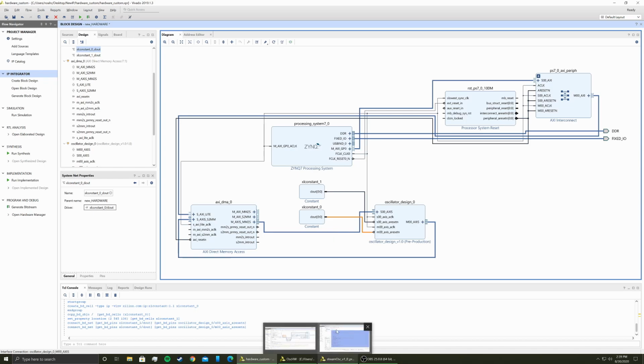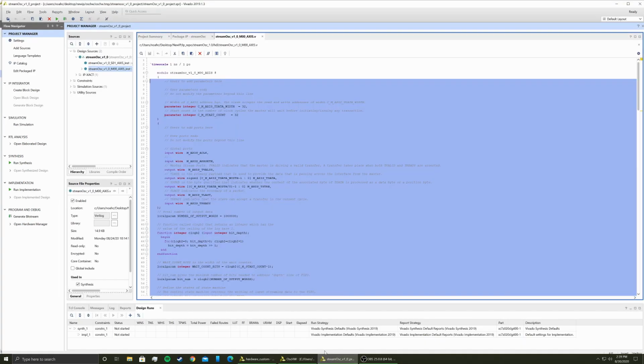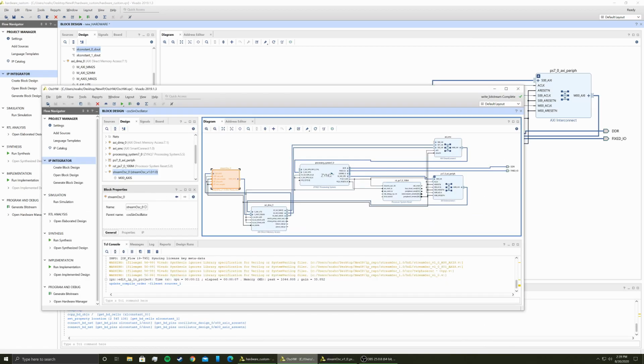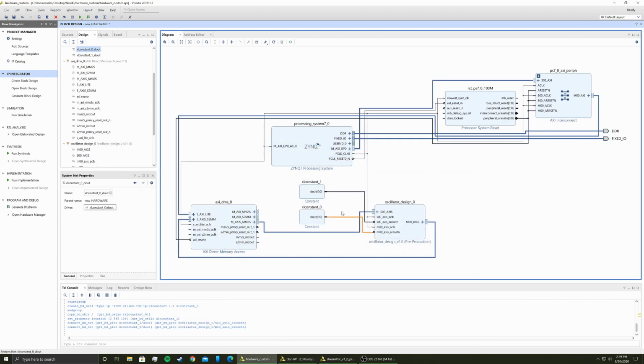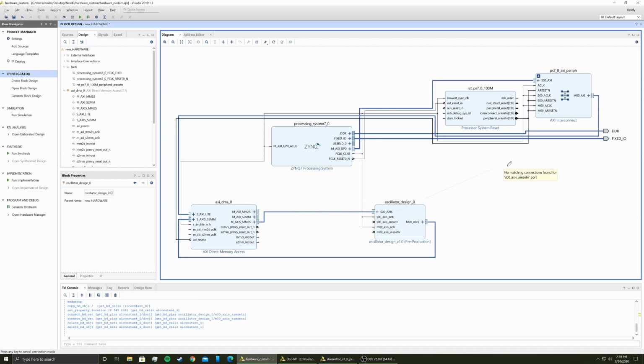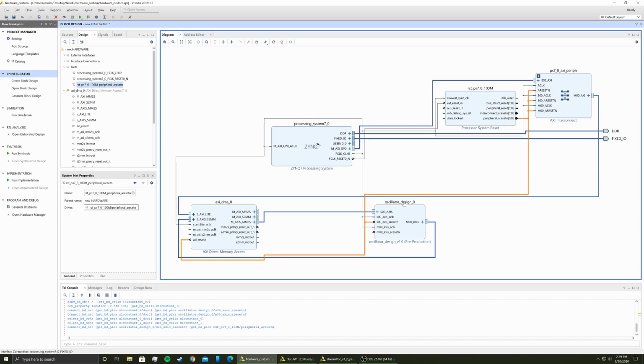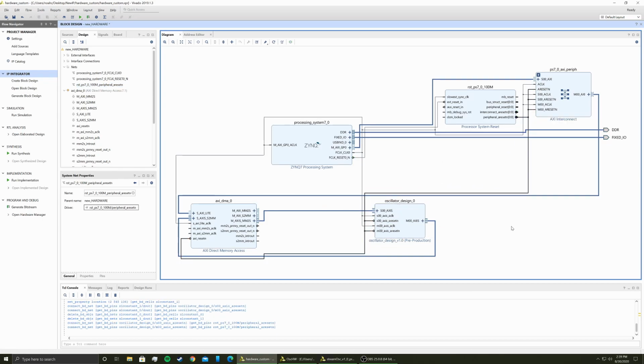Looking at my actual design, which I can pop up right here, that is not quite it. Here we go. This is the actual one I designed, and this one I kept the reset ports in. If you want to use the reset as well, you can just connect the reset ports up to the reset signal found within your AXI interconnect. So just peripheral reset, it'll allow it to reset with everything else. It's also an option, and we'll just leave it as that.